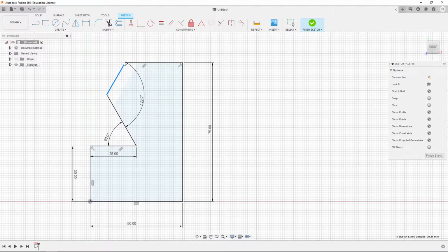If we see what we're trying to do, it allows us to make it smaller or bigger because there's no set length. If I dimension the top line, then it'll be locked in place. If I dimension this line, it'll be locked in place. Or if I dimension this line, it'll be locked in place. So any of those lines, we have to decide what we're going to do.